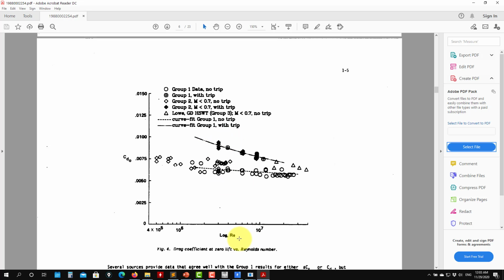So as you look here at the Reynolds number, 6 million or whatever you are using, and then you compare, you will see that you will fit better with this curve. Okay, this is very important. As you are comparing with experimental results, you need to see what kind of data you are getting, if you are getting natural transition or forced transition.